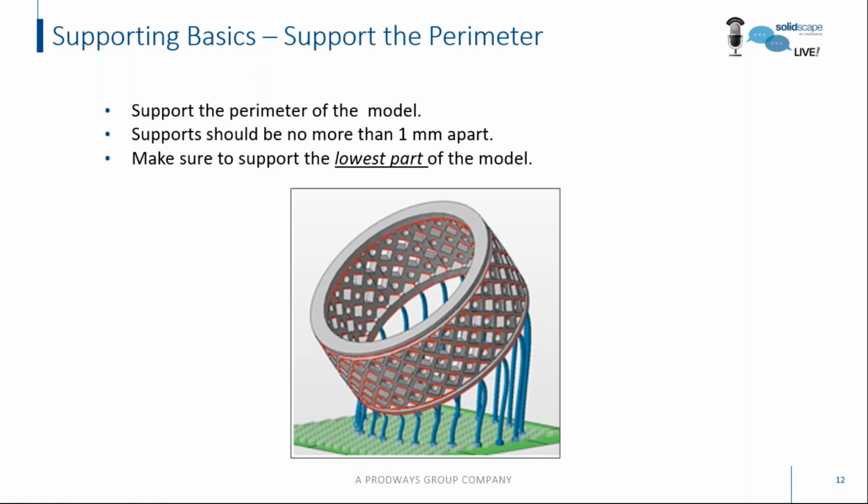Make sure to support the perimeter of the model. Remember, support should be no more than 1 millimeter apart. And make sure to support the lowest part of the model. Any unsupported areas may deform.